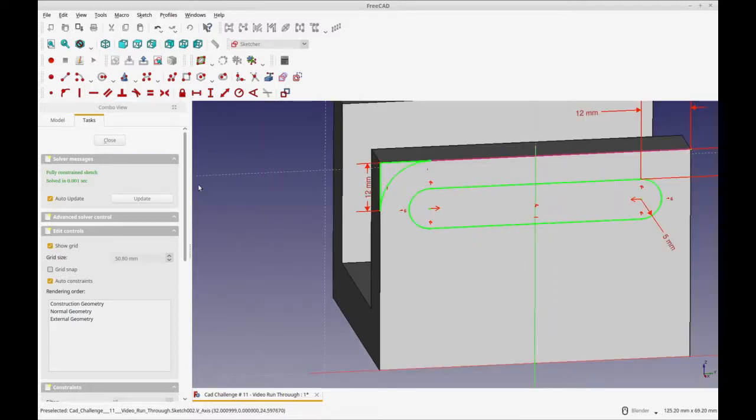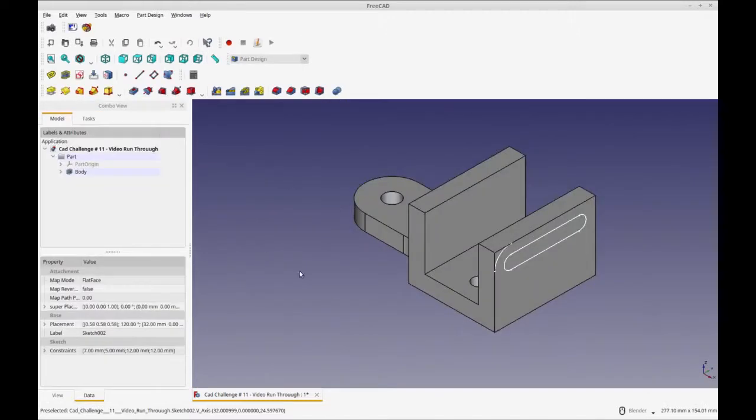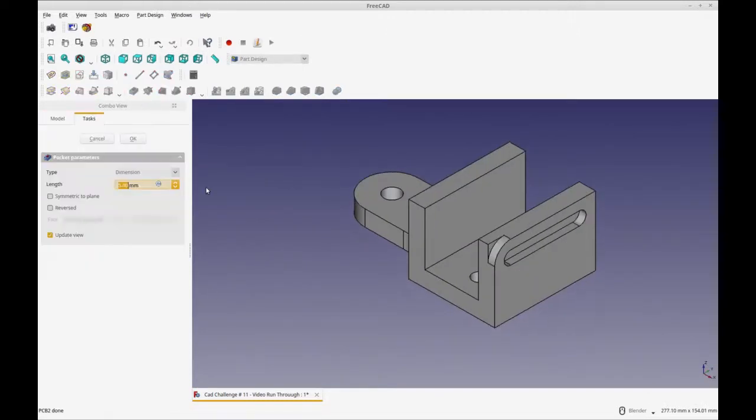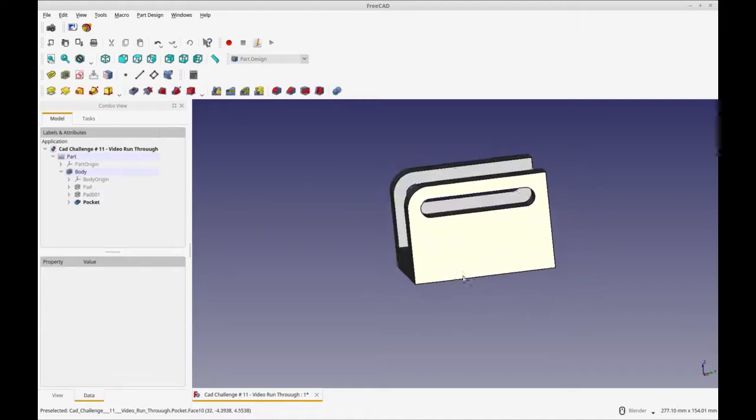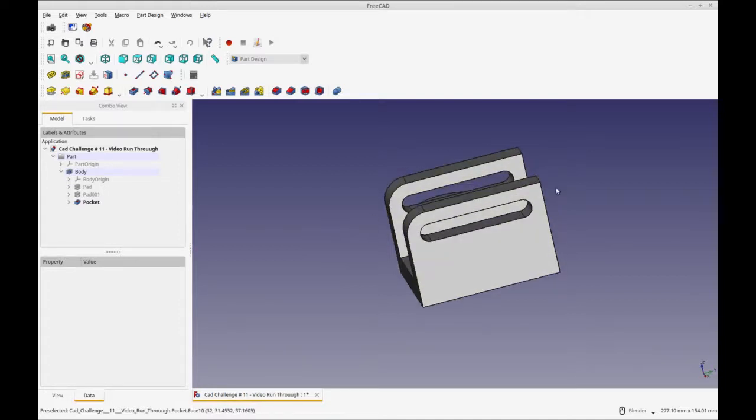So that's what I'm going to use as my sketch, and now we'll pocket that. The pocket will be a through all pocket, and you'll see how that would kind of get our fillets there. The reason that you might do that is it's easier to understand these relationships within the sketch than if you have to do it in the sketch and then in the fillet. But it's probably better modeling to do a fillet.